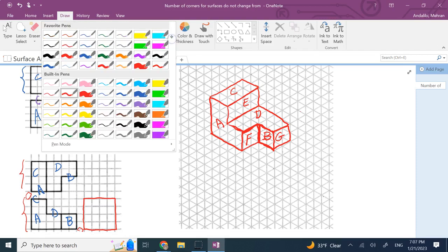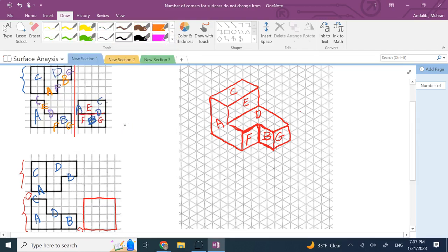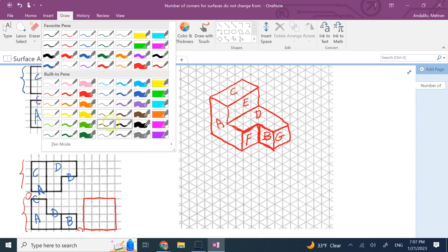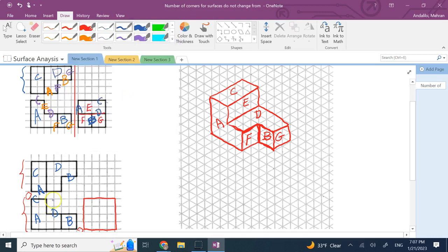Now let's go ahead and draw the right view if we can. At least start with A, B, C, and D. But what is A? Where is A? Well, let's look at A first. There's a color here. Where is A? Well, if I project A onto the right view, clearly it has to be what? We know in one view it's an edge, in one view it's a surface, so in the other view it has to be a vertical edge. And we know, we discussed between the left edge and the right edge, A has to be the left edge, so I can see it in the front view. So this guy here, from here to here, that is A.